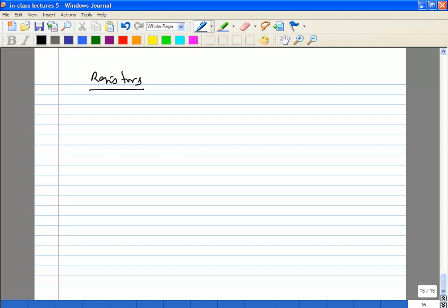So you have 5 or 6 different kinds of resistors. Many of them are based on silicon itself. So you have N type, you have P type, you have different kinds. There is something called a silicided resistor. Silicided is basically a polysilicon piece, and then you add some metal deposition over that to reduce the resistance. The metal forms a silicide compound with the silicon, and that reduces the resistance.